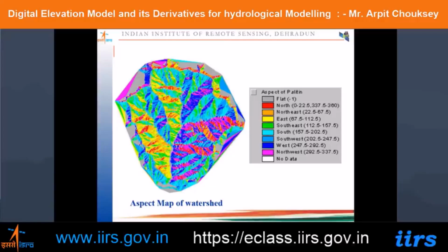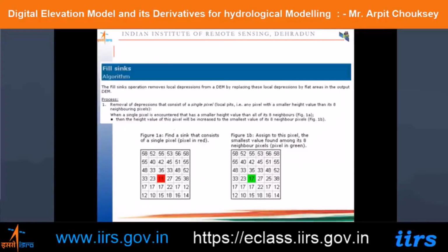The resulting flow in a grid is then usually interpreted as being proportioned between the two neighboring cells. So that's how the infinite direction can be created, and the steepest direction downslope will be the direction of flow. Generally in our hydrological modeling software and other GIS software, only the D8 algorithm is applied. This is the flow direction map of a watershed shown in 8 different directions of the flow.